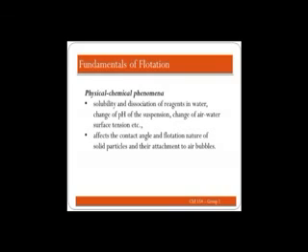Next is the physical-chemical phenomena, which is a very important phenomena that occur due to the addition of reagents. These include solubility and dissociation of reagents in water, change of pH of the suspension, change of air-water surface tension, and many others. These also affect the contact angle and flotation nature of solid particles and their attachment to air bubbles.